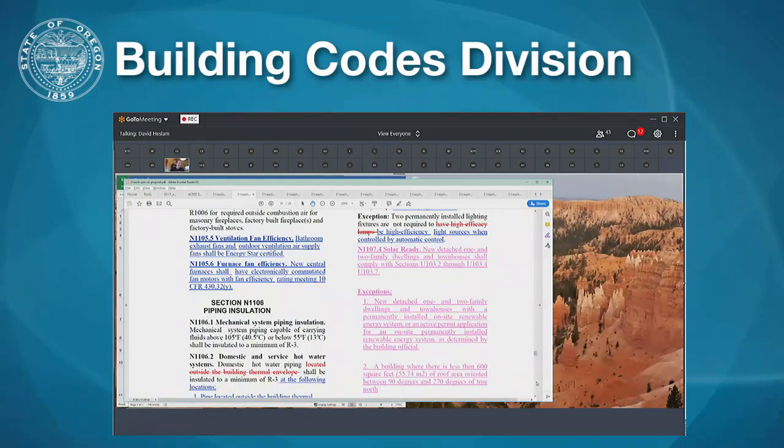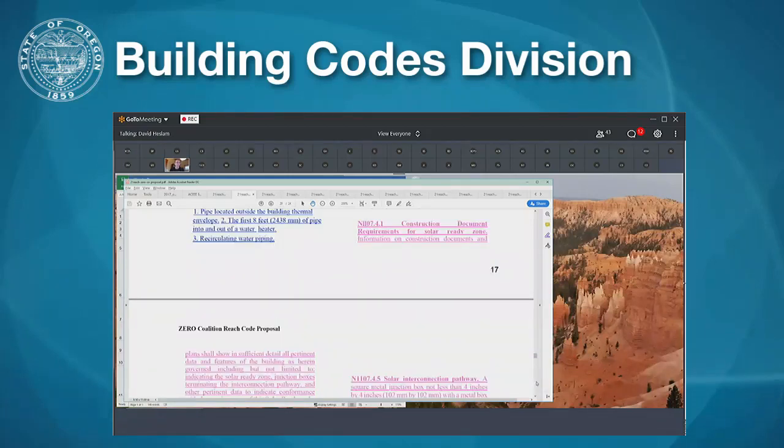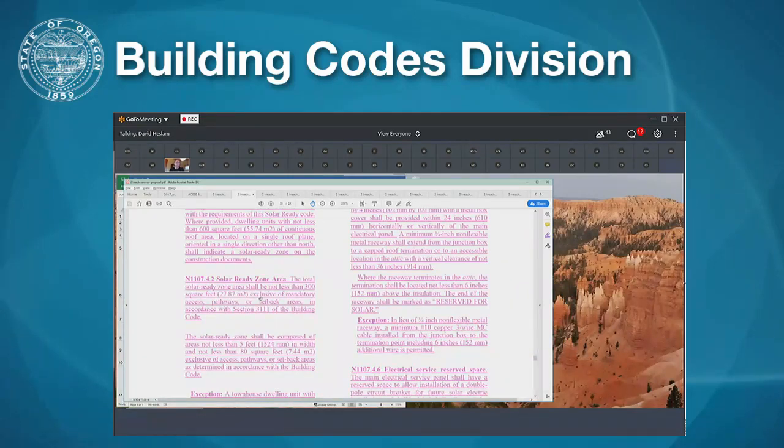At the end of the process for the base code, it ended up being just the chase. But the space means there has to be a predetermined identified space on the rooftop for panels to be located, or somewhere else on the property. There has to be a space for panels of a minimum size, and then there has to be space in the electric service panel, and space on the wall for an inverter to hang.